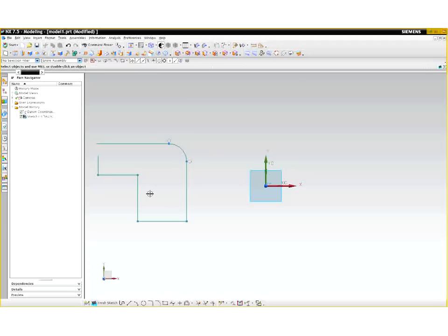What I'm going to show you now is called the fixed constraint. It's a geometric constraint. Our constraints are accessible to us through this bottom menu. It's like two parallel lines and then the perpendicular lines also. Let's go ahead and click that. And you see, immediately when I click it, we have these red lines that appear out of the points. These red lines are degree of freedom indicators. That's telling me that this particular segment can move up and down, left and right.